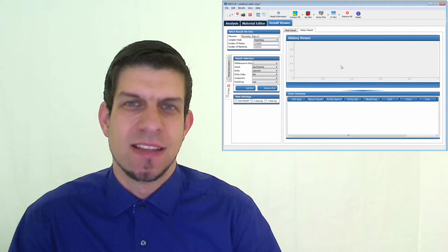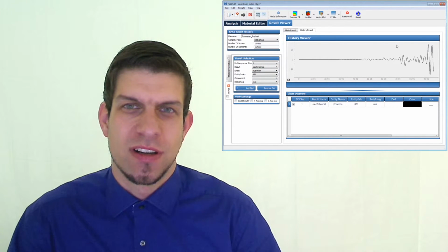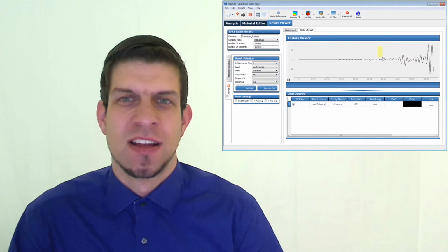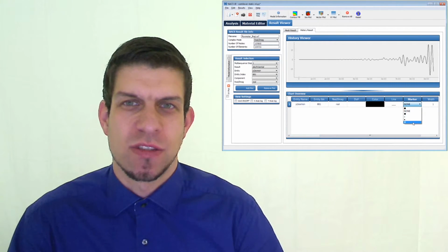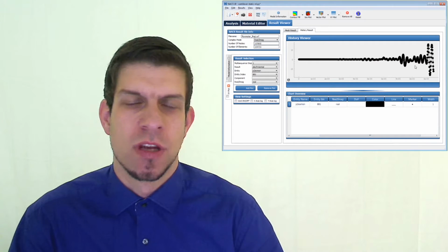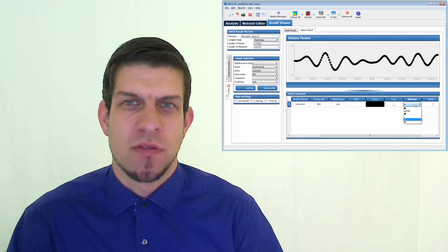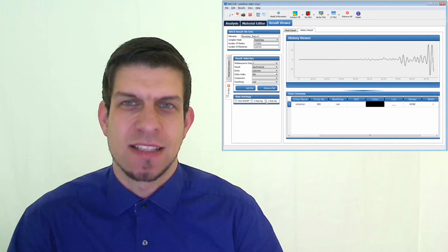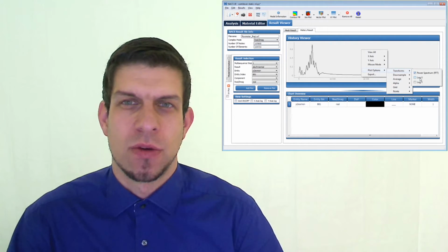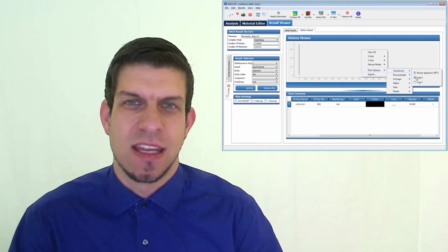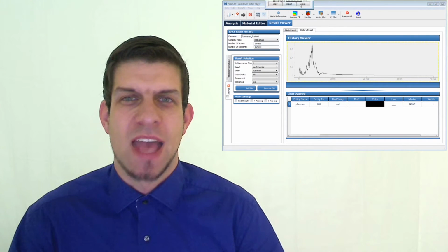So now you can easily zoom into your analysis results, like the monitor point displacement, and there you can also see a transient domain. You can automatically compute the FFT spectrum of it. You can modify the axis scaling between linear and logarithmic scaling. You can turn on a grid and easily turn off the grid. You can change line styles easily, and mainly you can also export the graphical result into a graphics file.